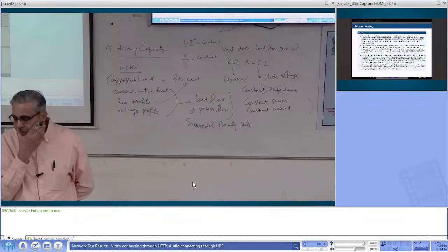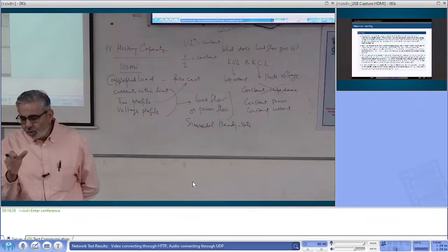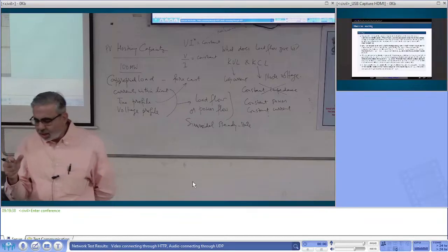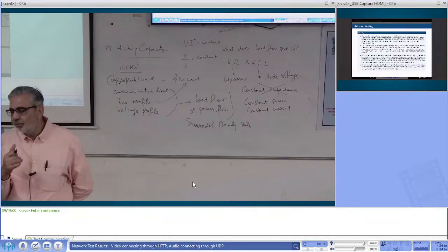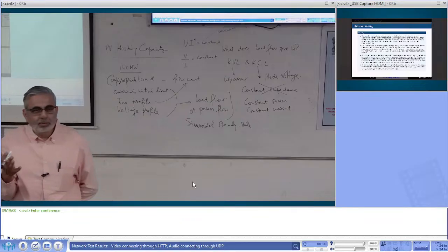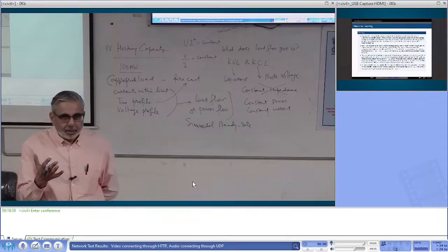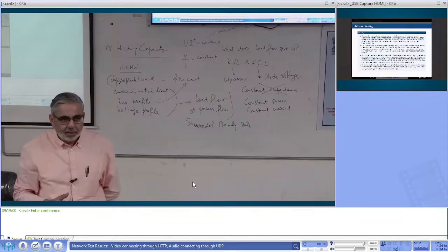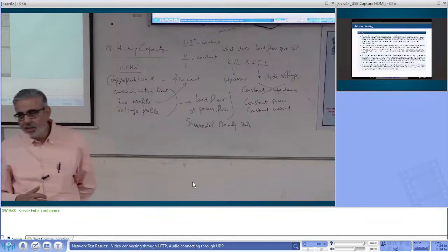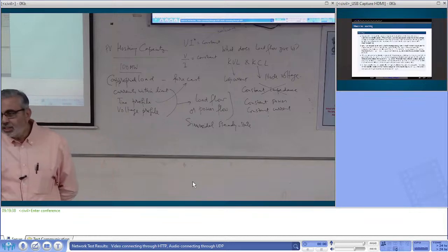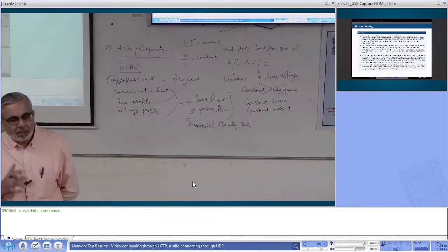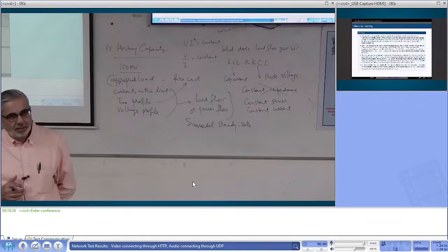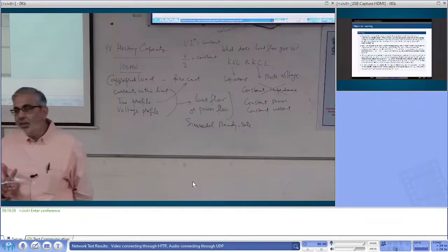So we assume that no matter what transients occur, when you integrate dynamics with load flow, in 10 milliseconds they will die down. I mean, it's up to you to accept that assumption or not. जैसे कहीं voltage बदला, in one of the stations the voltage changed. We assume that in 10 milliseconds it will achieve steady state. The transients will die in 10 milliseconds or 5 milliseconds or something like that. So that is one very big assumption.